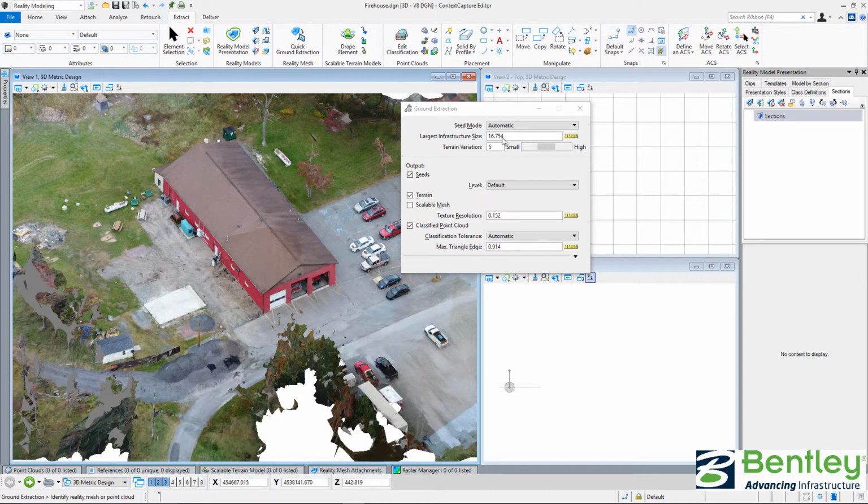This process is going to create tiles and compare tiles to the sides of that one tile. So if this number was, say, 5 meters, and we had small 5-meter tiles coming on this rooftop, and it looks to the right and looks to the left, it would say this must be bare ground, and it would think that this is a giant mound of dirt. Now, when you deal with photogrammetry, you can have this with large tree clusters that appear as ground because photos do not get through. If you are dealing with LiDAR, light detection and ranging point cloud, you will get many shots that have protruded through the tree canopy. So you'll get some bare ground shots on that. And this process would be great through vegetation if you're using LiDAR.